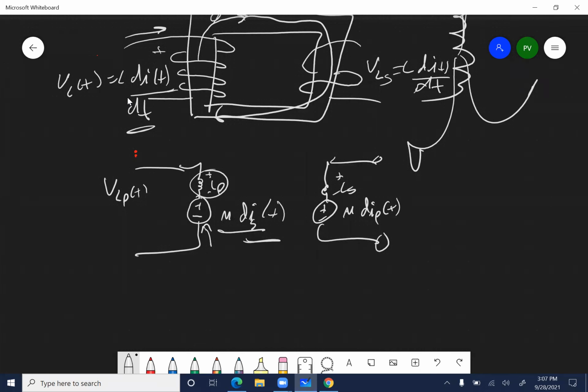And that's going to essentially make this term dominate. It's going to be a higher and higher percentage of the element that's going through there. And that also is going to drive this, because as I pull more secondary current, my primary current also has to increase to be able to make up that difference. So now this voltage here gets to be higher and it pumps out more energy, and that's essentially how a transformer works.